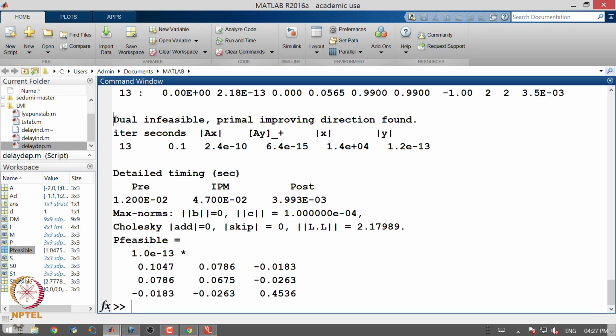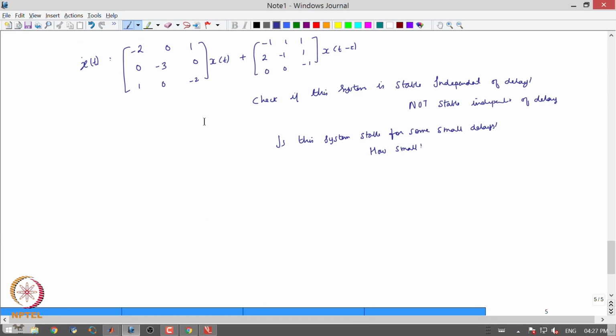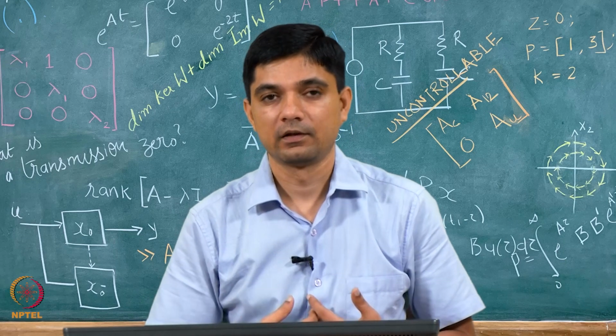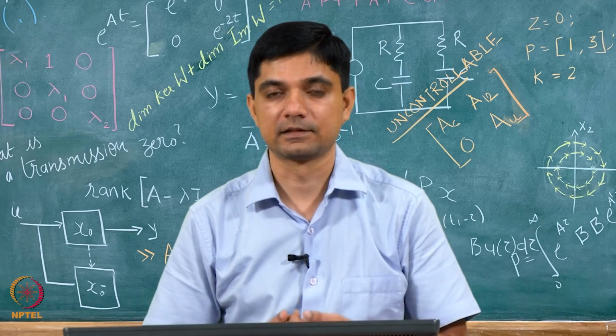Oh, no, some infeasibility condition, right. So, two things that I found out: for point 1 it is stable, point 3 is stable, and for tau equal to 1, the system turned unstable. Okay, and then maybe you can just write a little loop to check for the maximum value of tau or D that the system is stable.